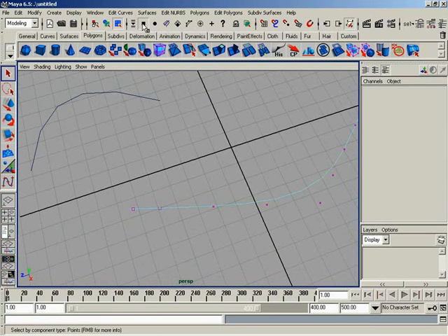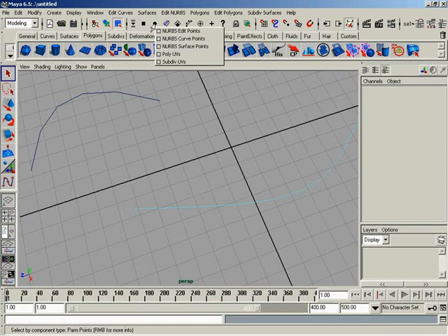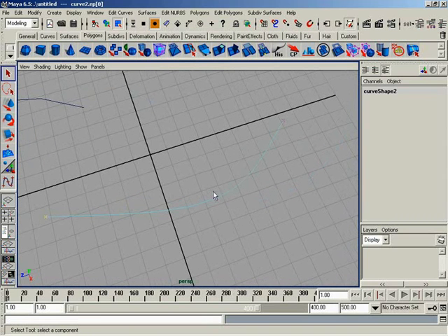Now let's take a look at edit points. And the way I want to do this is I'm going to come up here to my points. I'm going to turn them off. That's why all the CVs go away, but I'm still in a component mode. Now let's come over here to the second option, and this is by parameter points. Let's go ahead and right-click, and I'm going to turn on NURBS Edit Points. Boom. There's an edit point. It's a little X. There's an edit point, and there's an edit point. I better have 3. Why is that?